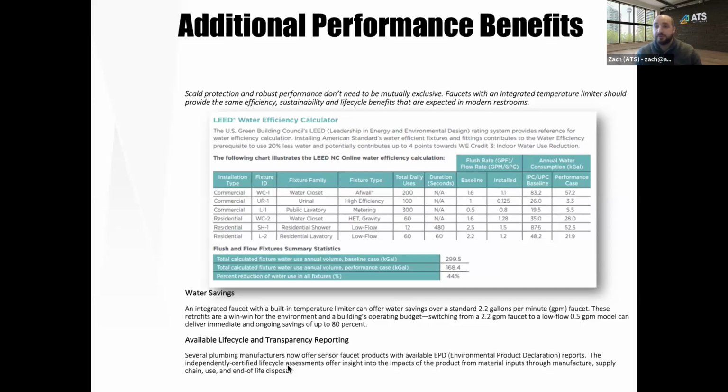You need a certain amount of flow through it in order for it to work properly, and it couldn't react. So that's where some of those temperature effects you were talking about earlier can come in, where it's kind of bypassing the actual mixing valve's element, and that's why these point of use ones are a nice meet in the middle. You have that lower flow rate and reactivity instead of having a larger mixing valve that can't be activated by a single faucet.